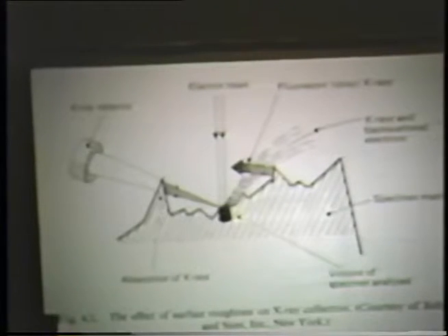Now, the specimen surface topography. X-ray photons travel in straight lines, and care must be taken to ensure that there is a direct line of signal between the region of the specimen being analyzed and the X-ray detecting system. Whereas most metallurgical and geological samples can be prepared with a very smooth surface, this is rarely the case with bulk biological specimens, and surface irregularities can easily obscure and absorb emitted X-rays, as can be seen from here.